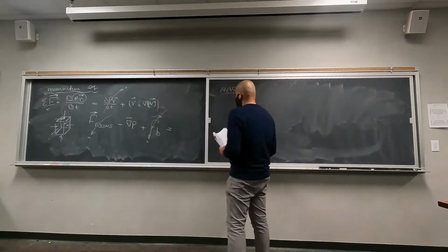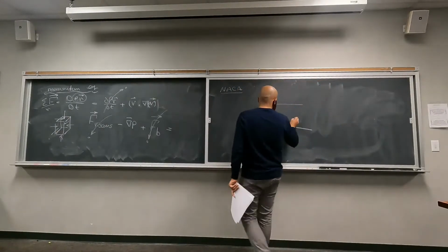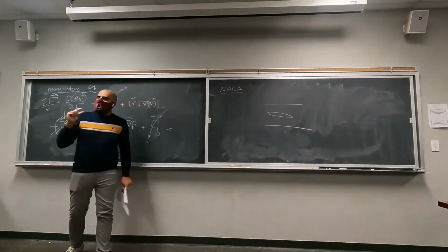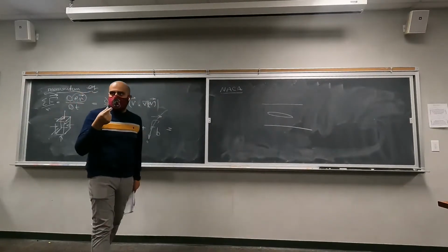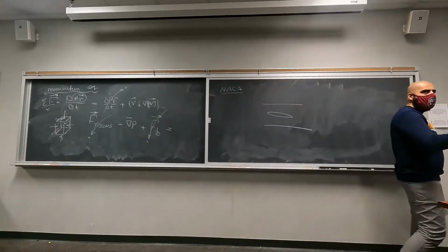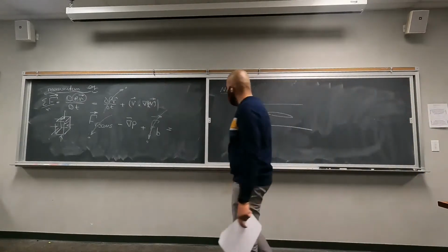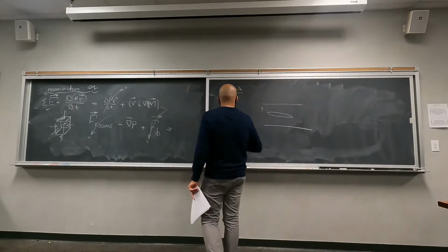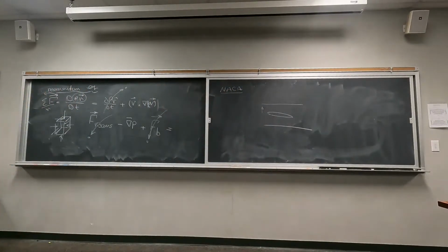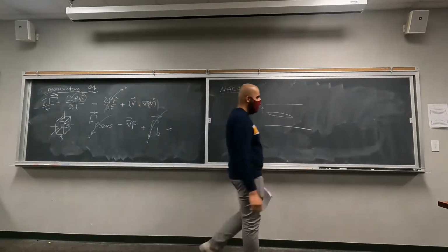So what they did was this. Let's say this is the wind tunnel. The first thing they did was to change the angle of attack, make very small changes in the angle of attack. And also, they started with thin airfoils. So the changes of momentum in the y direction became unimportant, and their contribution to drag became unimportant as well.